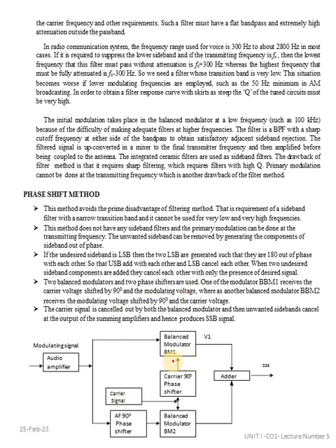The phase shift method is the same as the generation of SSB. That is, we use this same block diagram to derive the SSB equation. The modulating signal is given directly to one balanced modulator, and the signal is phase shifted and given to balanced modulator 2. Similarly, in the carrier also, phase shift is introduced. With the help of this summer, we can eliminate the unwanted sideband frequencies. So this is the basic principle of the phase shift method.